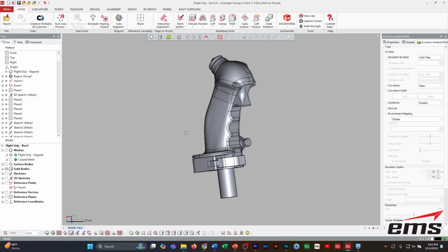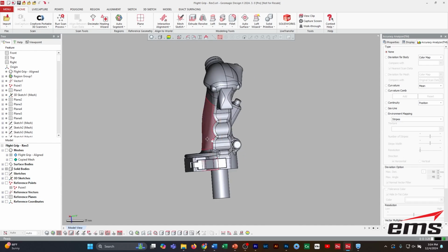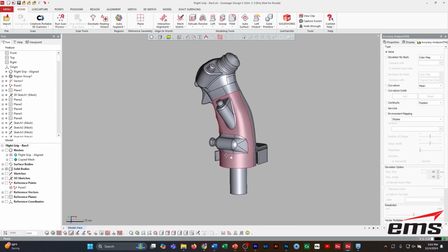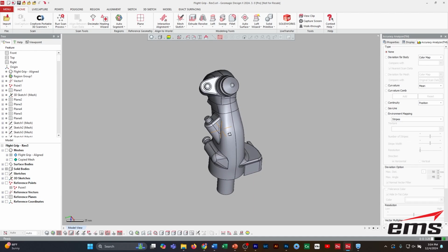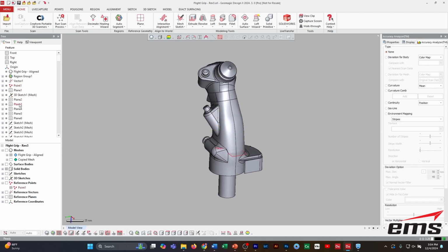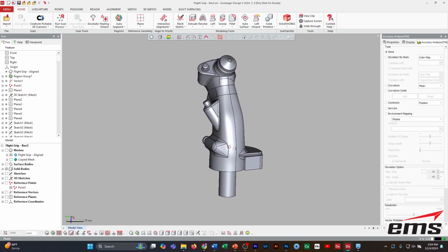The disadvantage is it takes a lot longer to build this type of model. For example, the auto surface model might have taken 15 minutes to clean up the mesh and surface it up. The hybrid model maybe take an hour. Something like this could easily take 8 hours or longer to build this model. But what you end up with is a much more intelligent model.